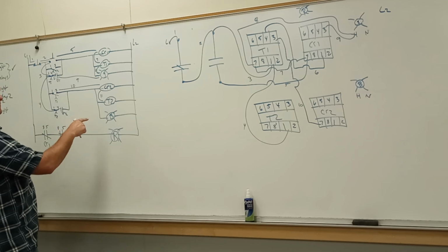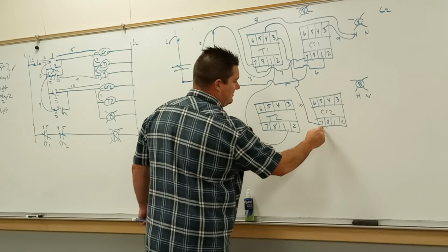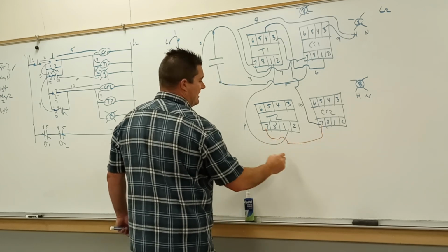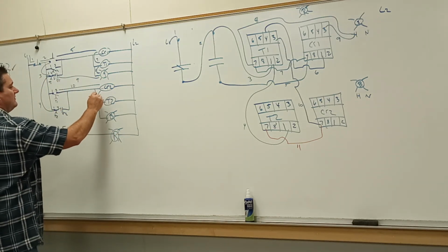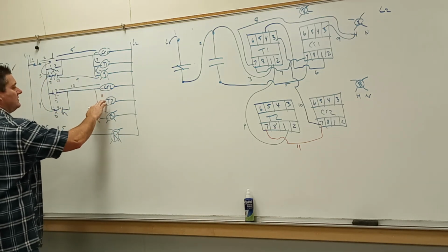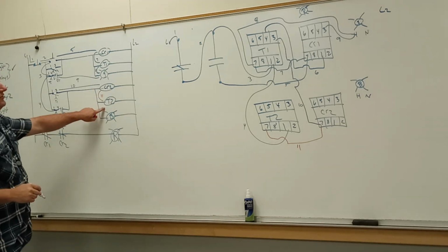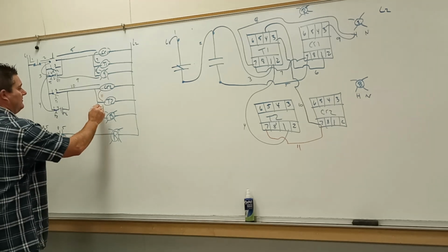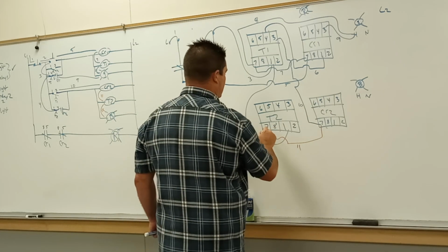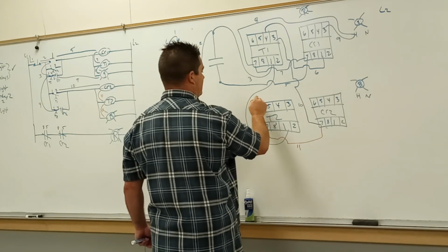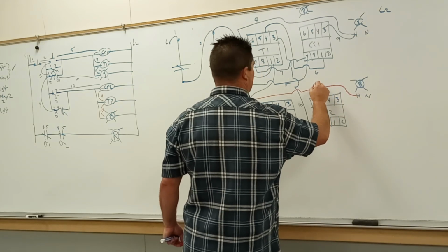Alright, now I have control relay 2 to timer 2, number 11. Control relay 2, timer 2, wire 11. I'll draw this one here. I'll turn this one to red. How's that? Timer 2 coil to blue light, number 12. Timer 2 coil, blue light. Number 12.